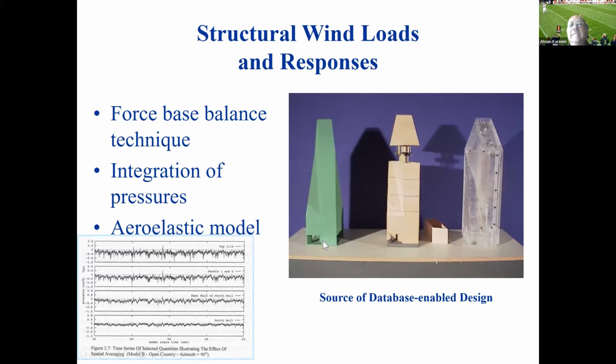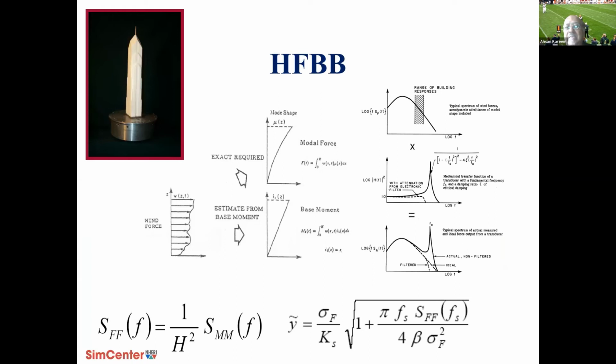So what it does is that the integrated effect of all the loads is monitored by that balance. And it so happens, I won't go into the details of the study here, but this is the building model on that one. What happens is if you develop an equation for the modal force of a building, which is given by this very simple expression, and if you develop base bending moment caused by some arbitrary wind loads, they both happen to be only scaled by a factor of height of the building.